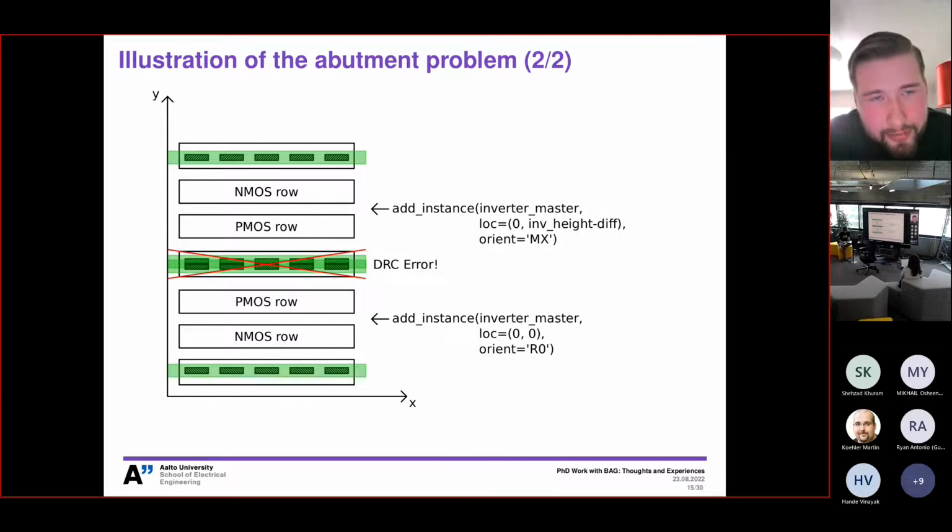And there's an argument saying that the spacing that originally exists is not too significant, but of course if you start to build massive systems using these analog base templates, then it starts adding up, and it will mean that you consume extra power and suffer a penalty to the area and speed of your circuit. Okay,